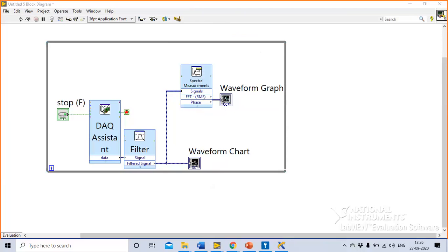Okay. Now, once we do the spectral analysis of it, we will understand the frequency component of the signal of interest and various other frequency components of noise signals. Now, let's say if it was a particular noise signal, let's say 50 hertz or 100 hertz or 200 hertz noise signal, then that would have shown up as a peak on the spectral curve.